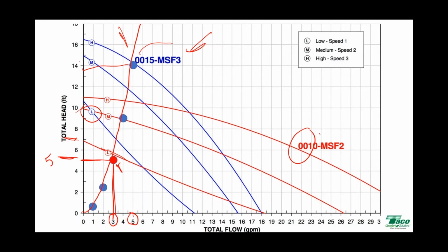So my delta T in this case, the best case delta T I'm ever going to see in this example, is probably going to be about 12 degrees. And that's going to be on the coldest day of the year, the so-called design conditions. So it's going to be 12 degrees, best case scenario. Most of the heating season, because I don't always need 30,000 BTUs, I'm going to need considerably less. Most of the heating season, gang, you're going to have a delta T that's less than 5 degrees. And that thing's going to short cycle like crazy.